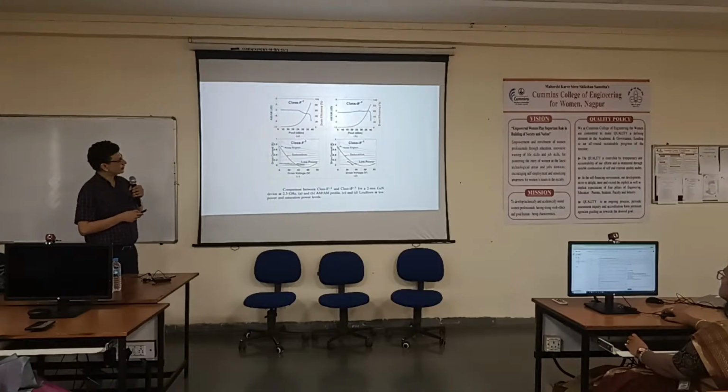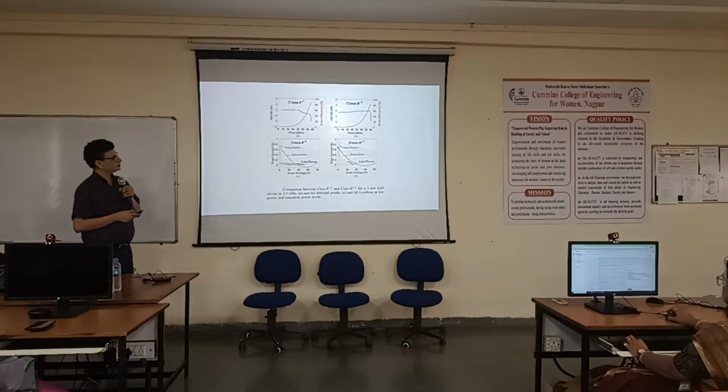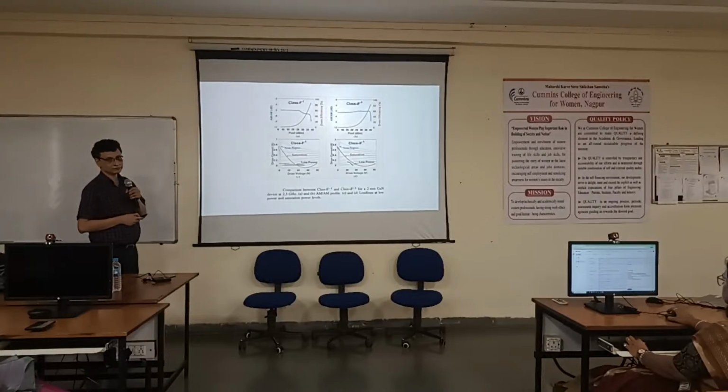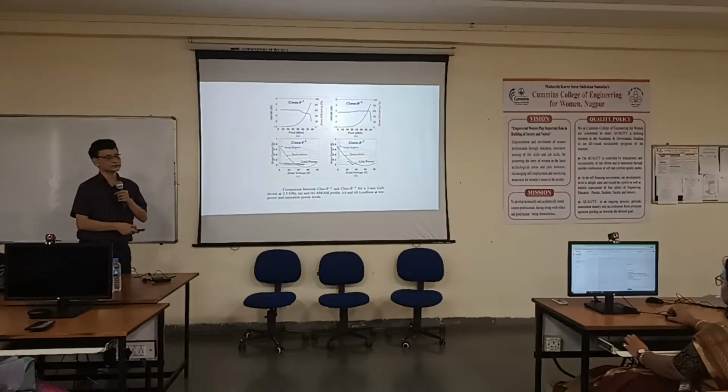So ideally, any amplifier should have this line. If I plot the AM distortion, it should be zero, ideally. It should stay at zero for all output power levels. But in reality, what happens is it goes down. The output power goes down and this distortion appears like this. Now in this class F inverse amplifier, this distortion is manifested in two ways. This is called a double inflection point. So there are two dips, one dip here, one dip here. And this we solved using the methodology that I just described.